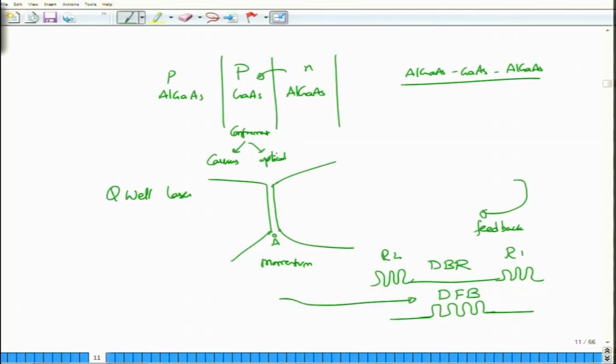Most practical lasers that we use today are DFB quantum well lasers, and this provides both wavelength selectivity and feedback. Wavelength selectivity is important because, as you know, the radiation spectrum of a laser or of a semiconductor material is quite wide, but by incorporating the feedback in the form of a DFB or a DBR laser, it is possible to have an extremely narrow line width laser come out of this. Okay. So, this is what you would actually have in the output when you put a wavelength selective feedback mechanism into the system. So, this is all about lasers, and thank you very much.